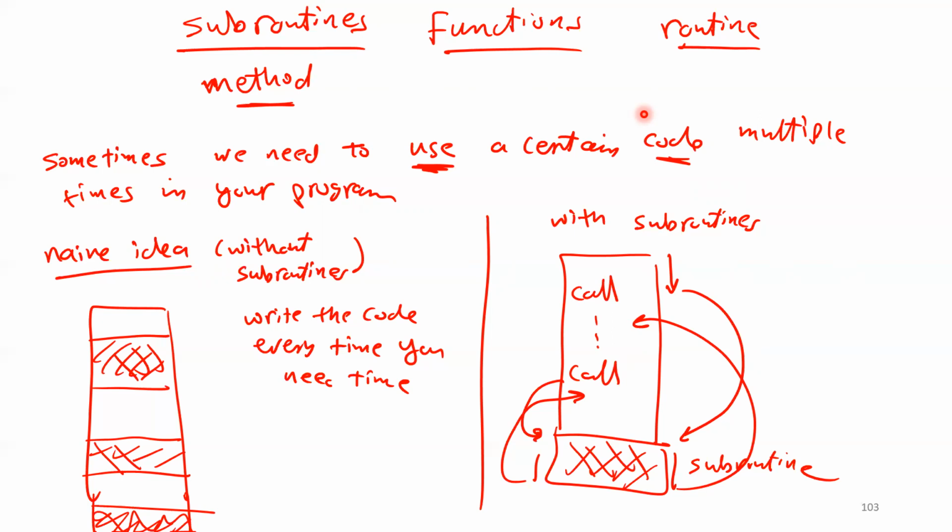You remember when you have an initial program, and I tell you to remove this one and put something else. If you look at the instructions written there, you will find one of the instructions, load stack pointer with 4,000. So it's already there. Anyway, number 3, stack pointers are very important to implement subroutines. Is that okay? So without stack, we cannot make subroutines. Why? I'm going to explain in this section, so don't worry about it.